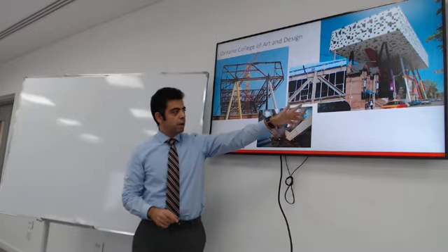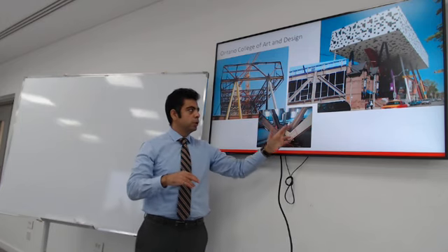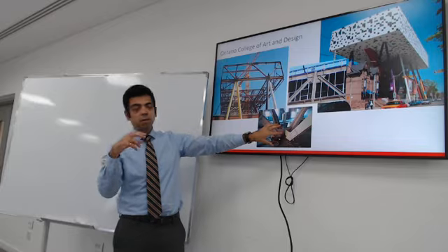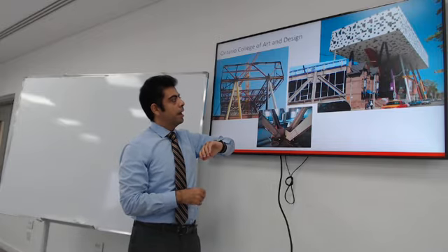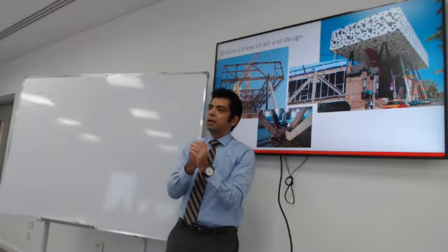These parts will come in pieces. You use the crane, you line them up, you use the bolted connection. This is how an inside connection looks like. That's how an outside connection looks like. And there is a fair bit of detailing that goes into it.